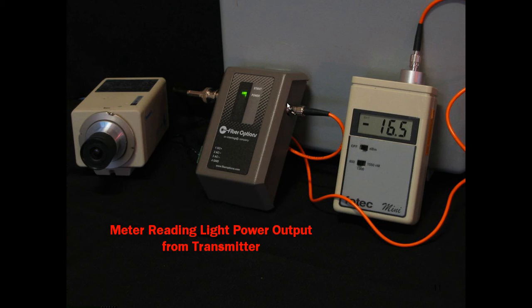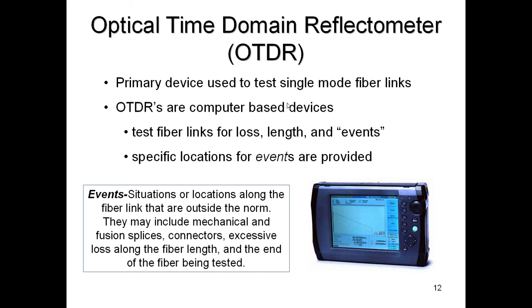So fiber optics can be very, very simple to troubleshoot. Go to the transmitter first, check the power output, reconnect the fiber that's hooked up to it, go to the other end, check the power that's hitting the receiver, and if there's not enough light coming out of the transmitter, the transmitter's bad. If there's enough light hitting the receiver, then the receiver's bad, right? Logically, it's pretty simple to consider.